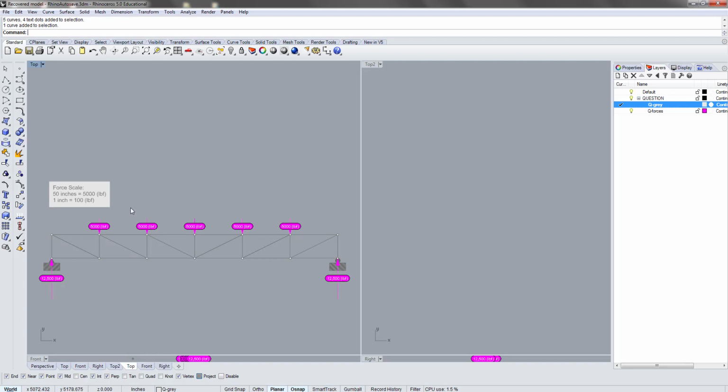So now, the first step is always labeling the zones between the forces. Obviously the zone between these two forces is A. And if you keep naming it, it's going to be A, B, C, D, E, F, G as shown. That's between F and G, and this is between G and A. And now you go to the inside of the truss, and you name those zones by numbers. So that panel is 1, and you keep naming it: 1, 2, 3, 4, 5, 6, 7, 8, 9, 10, 11, all the way up to 12 as shown.